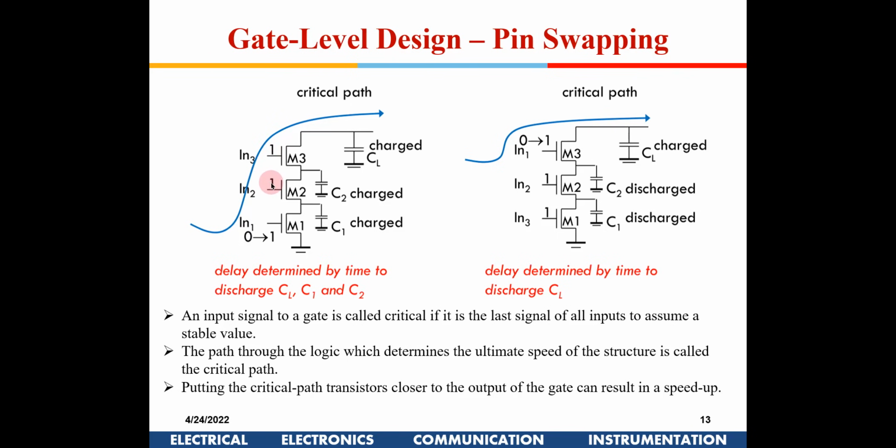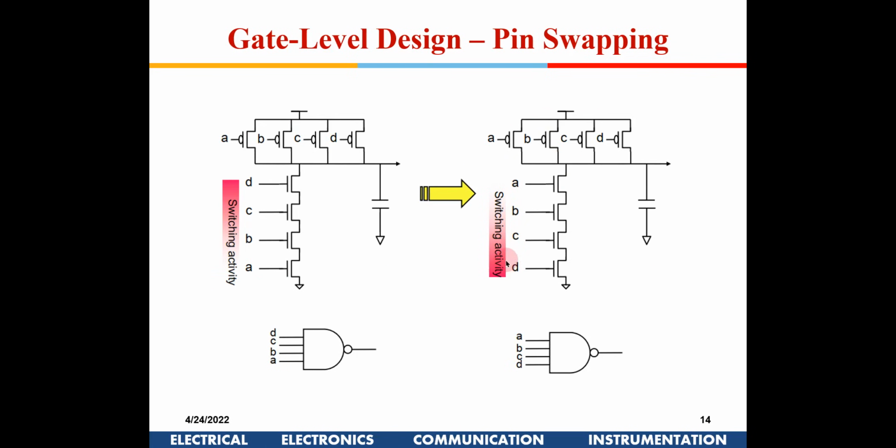Suppose these both are, now here if you see, every time this makes a transition from 0 to 1, right, and 1 to 0, if you keep a transistor out here, this capacitance will get charged when it is switching on, right, and then when it is switched off, this will be off again. So if you see here, it is wise to keep, let me show the next slide, the one which has got more activity in the bottom for low power.